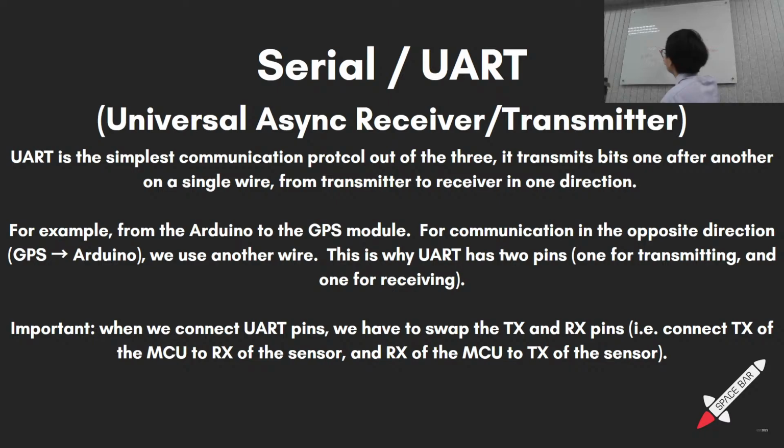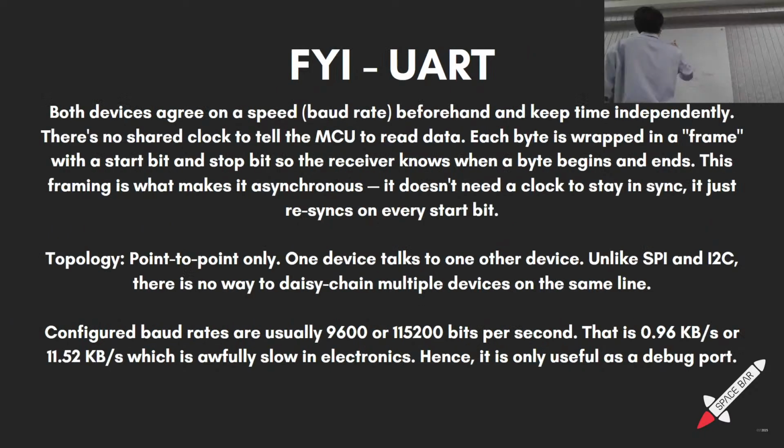Like this. Like the time taken, I should draw. Okay, so normally it's idle, then you've got the start bit here, then you've got your data bits here. Your data bits can be anything, so usually we denote them like this. Then you've got your parity bit. Then you've got your stop bit, which I believe is a high. Yes.